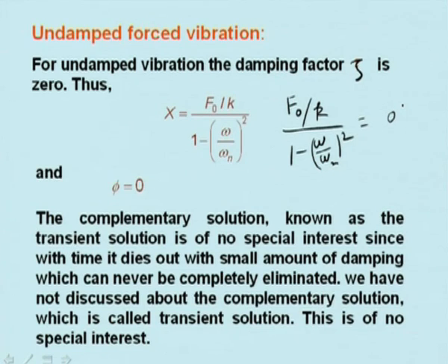That means if you have a spring mass system like this, with a very flexible spring, and you apply a force of a very high frequency, it will not be able to move. That means it will not carry out any vibrations. So this is the thing.